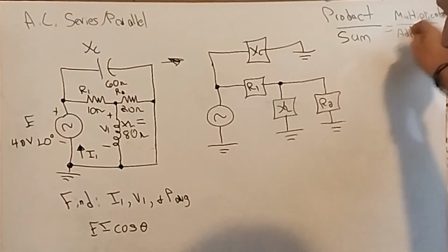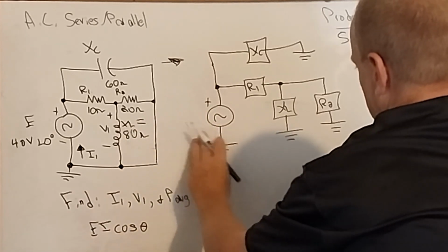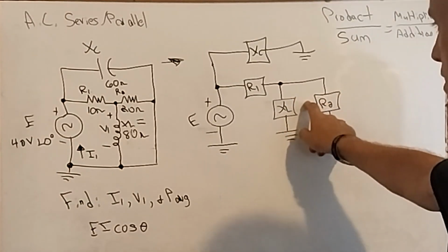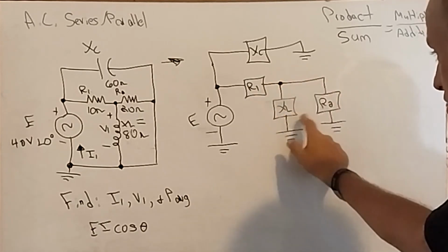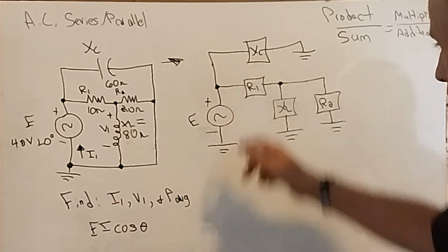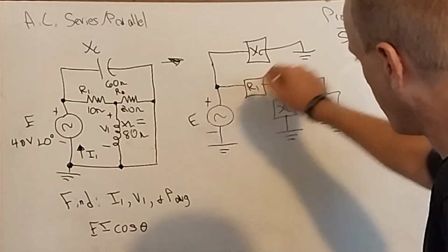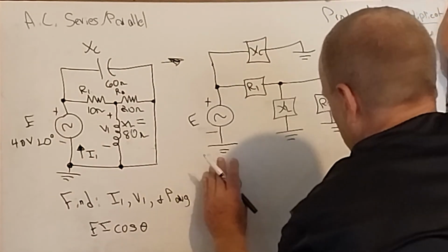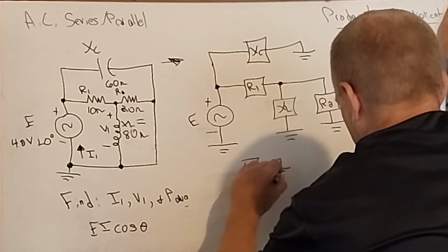And so now if we look at the circuit, these two are in parallel, and then whatever this becomes will be one value, and then that's in series. These two in parallel is in series with R1. So this total equivalent will be in parallel with X of C, because they share the same voltage point here. So if I redraw it again, let me put X of C here first, because that's going to be the top one.